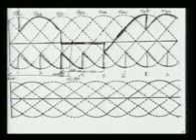So this is your DC output. The ideal case, when there's no overlap angle, this U is 0. The DC output in inverter operation is when alpha is more than 90 degrees and less than 180 degrees, and the valve voltage for valve 3 we draw here.